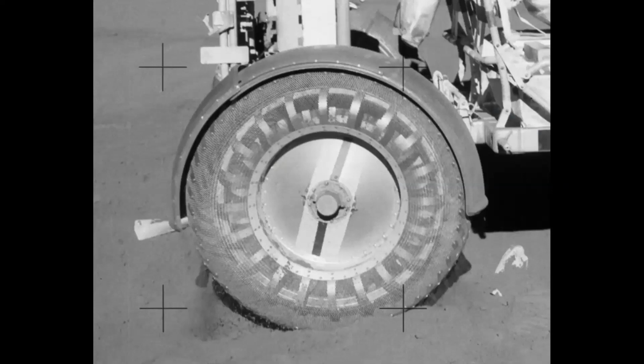Now we're going to talk a bit about trafficability. Trafficability, if you're not familiar with the word, is defined as the capacity of a soil to support a vehicle and to provide sufficient traction for movement. Based on experience of the Apollo and the Lunar missions, we know that almost any vehicle with round wheels will perform satisfactorily on the lunar surface, as long as the ground contact pressure is no greater than about 7 to 10 kilopascals.